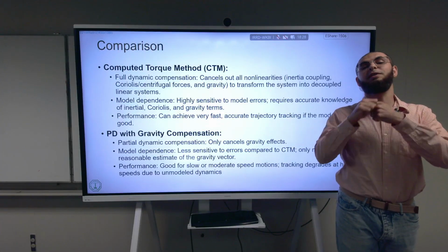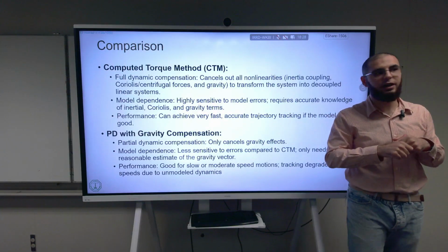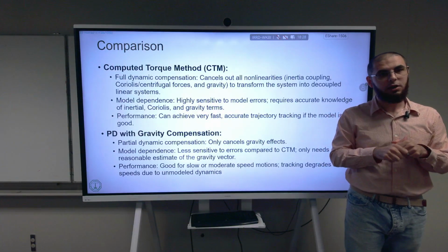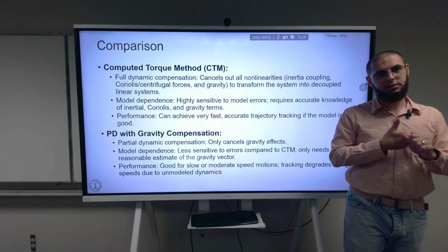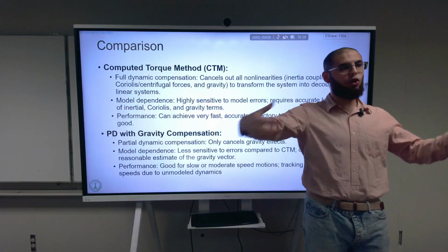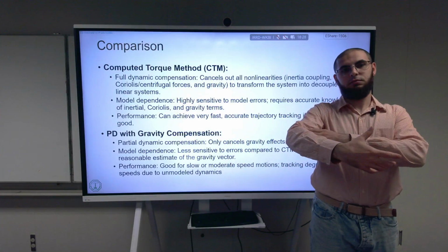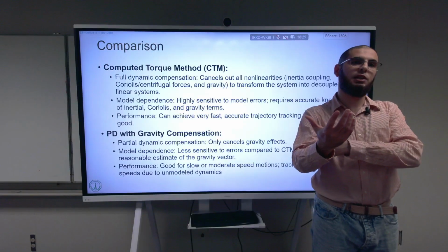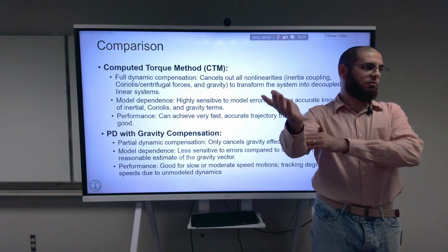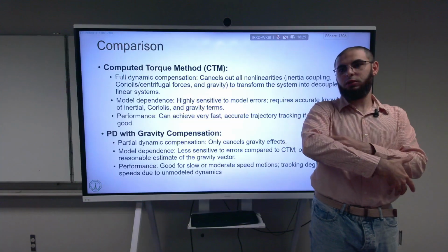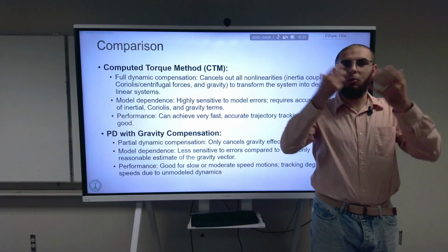That's one. There's even something worse than that people rarely look at, called modeling uncertainties. For example, I design a robot assuming I have no friction. And if I know what the friction is, I'm going to assume, for example, viscous friction. Is this the real friction model? No, it's actually called the model. It's an assumption.